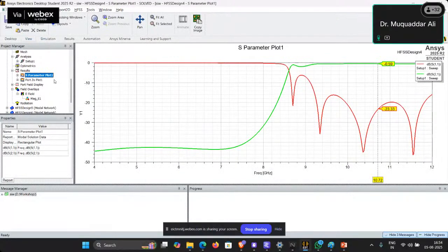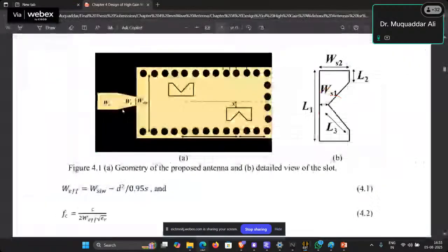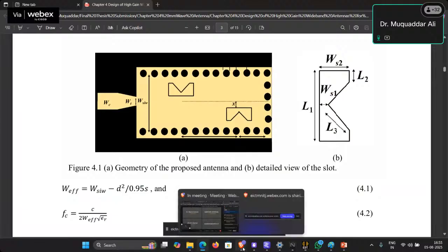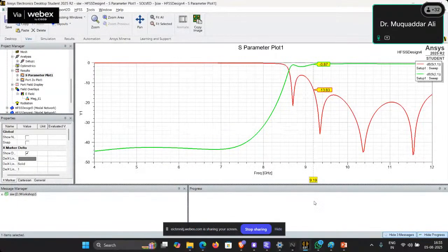Now we see, now the return loss is much better. So in SIW, what happens? The length, this transition length that I said should be lambda by 4. This transition length should be lambda by 4, but it will be only for a particular frequency, and for a wider frequency we are hoping that this taper transition will give a better frequency range, but we need to optimize